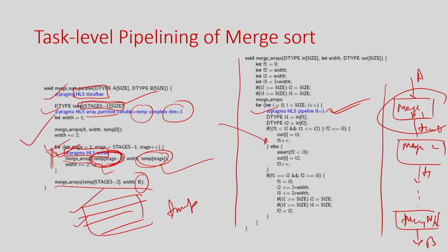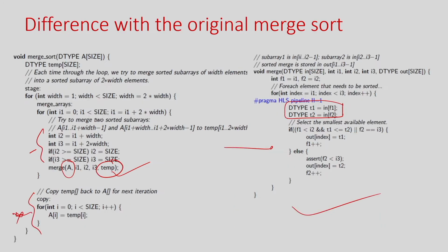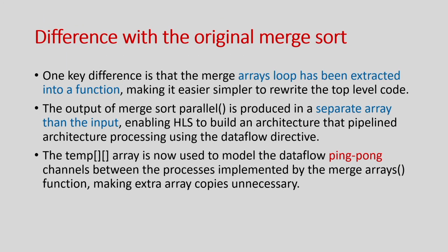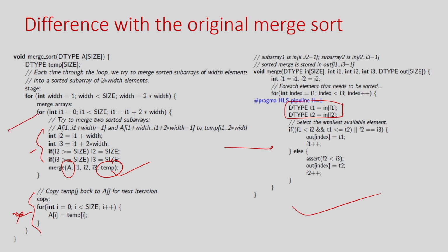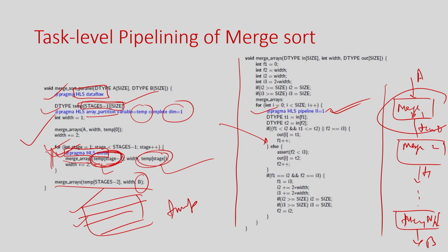Okay. I will strongly recommend you run this particular code and the base level code, and see what the difference is. You can also try to apply the same pragmas I talked about here in the top level code: you try to apply unroll here, unroll here, pipeline here, HLS data flow here, and you will see that you won't be able to apply HLS data flow because of these dependencies, and there is no data flow there. But if you apply it here, you can understand that this will give you efficient hardware.